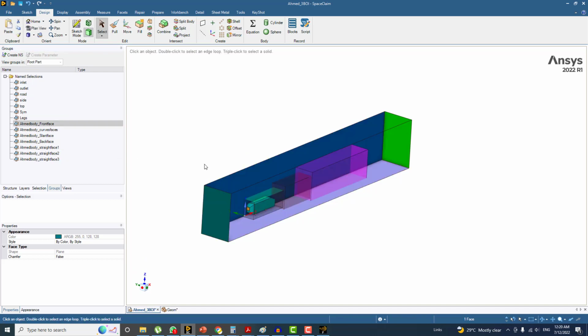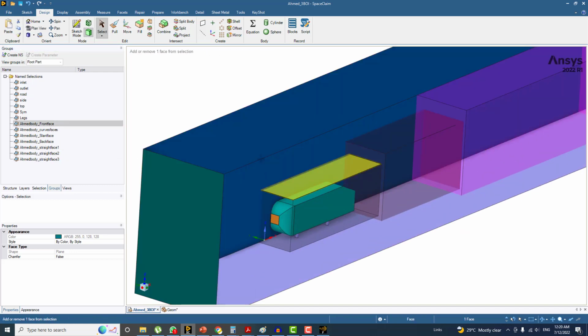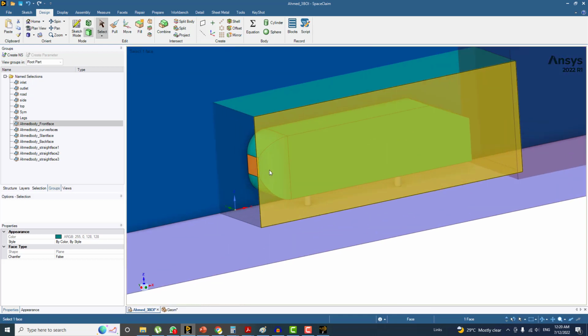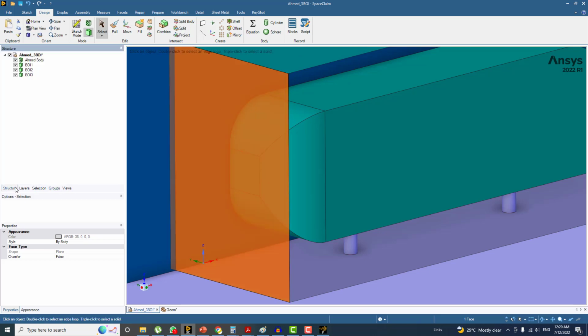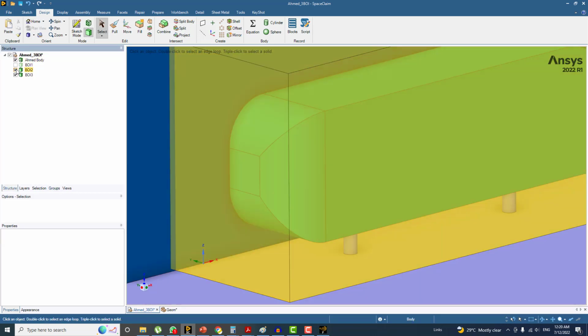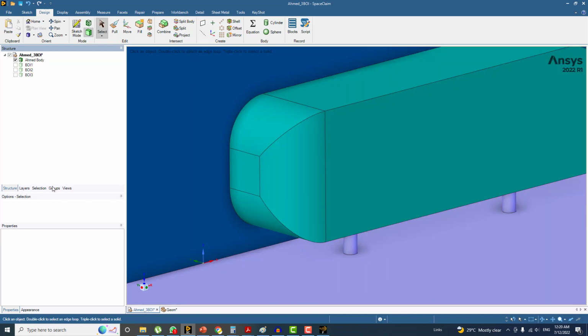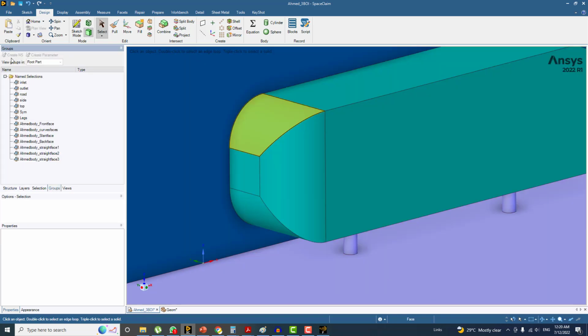And then I divided this MN body into multiple parts because we need the separate mesh, and it should respect these lines between the intersection. Otherwise, if you don't make the different boundary conditions, different groups or the name selection, the mesh will not be defined on these edges. Otherwise, these will be fused to each other and you will be getting a very diffuse mesh.